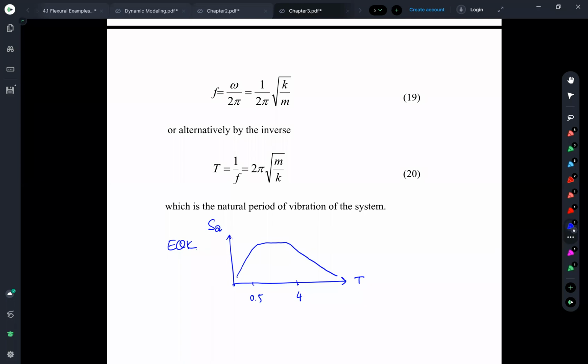So even though you build the same building, number 1 and building number 2, if your buildings share the same mass M, the values of the force called V1 and V2, the base shear from the earthquake, will be different depending on the period. Normally the natural period, the first fundamental period of the first mode, mainly controls the design. What is your period of vibration?